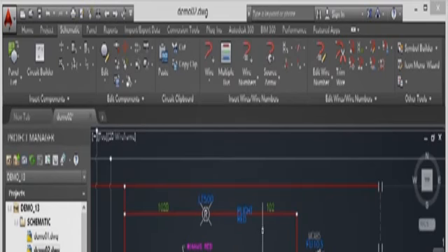And you'll notice here that this wire length has updated and gone back to one full wire length instead of two, where it was split here and here, where that light was originally. So that's how you use the Move Component tool in your AutoCAD electrical drawings to physically move components rather than scoot them like we did in the previous video.